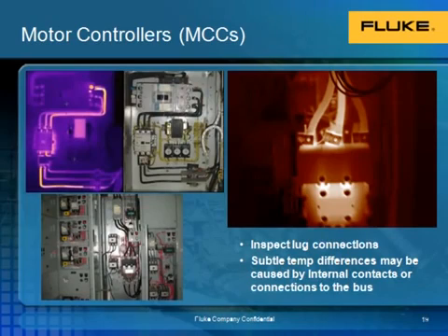A thermal imager works great for motor controllers or MCCs as well. As you can see in the images in the upper left there, very easily trace the heat pattern going throughout those connections. Check the lugs on these and also make note of subtle temperature differences, as it may be caused by internal contacts that you can't actually see.